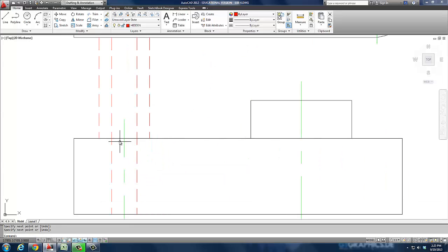Now, what I've done is I've made myself actually some construction lines, because I want a line that goes from here at, we're going to go 0.125, comma, minus 0.125, and it creates my diagonal line right there. And then I'm just going to bring that across till I snap to perpendicular and up to that endpoint. At this point, I can trim this line and get rid of that and just erase these two because, like I said, they were construction lines.